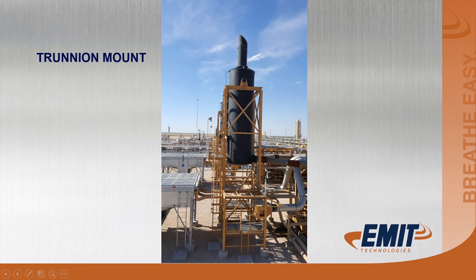Here's a trunnion mount housing. These were mounted up. These were 3616s, I believe. And so the housings were quite a ways in the air. The reason they're called trunnion mounts is they have a trunnion up here on the top, and they're free to move. What that does is allow this pipe to expand and contract, and this can swing back and forth.